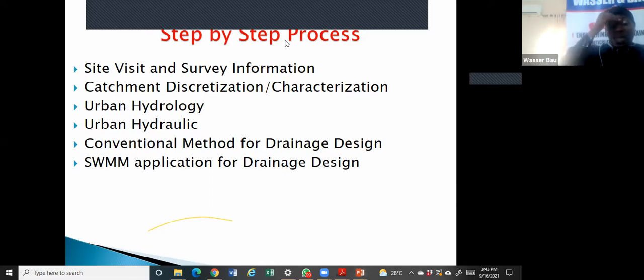Why this is important is that this is what will help you to get your Q, your discharge, based on the area. When you get your area, you get the intensity. If you multiply your intensity by the area, it will give you your Q. Okay, so let me just go to the whiteboard and say this. In our school days, we all know this formula. It comes in different variants, but they are the same thing. That your discharge Q is a function of your area, A, and your velocity.